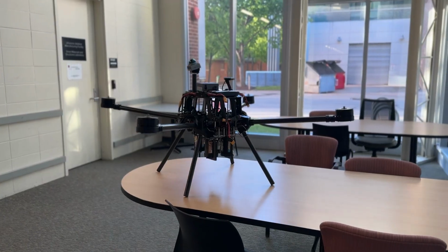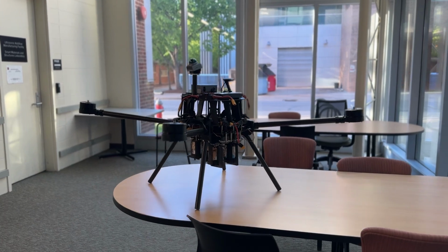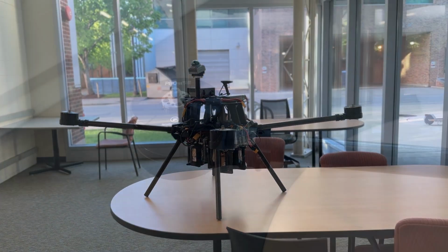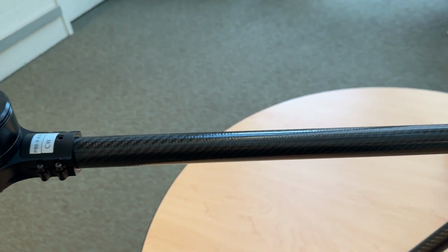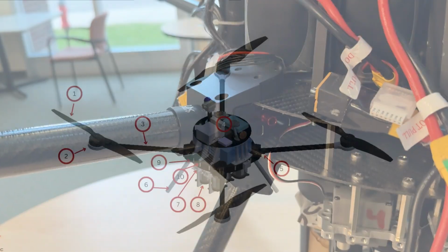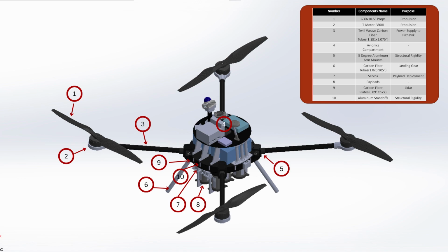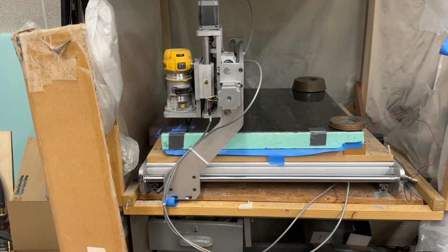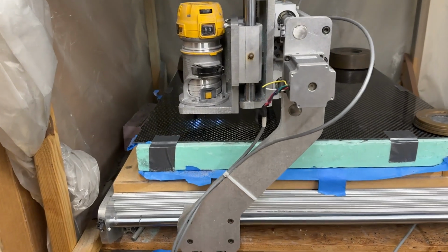The structure of our drone is composed of 3 2x2 12-weave carbon fiber plates, sandwiched by aluminum standoffs. This was chosen due to its high strength/stiffness to weight ratio. 12-weave carbon fiber tubes were used for the arms to provide minimal deformation under load. The plates were manufactured via CNCs, and automated saws were used to cut the tubes to limit human error.